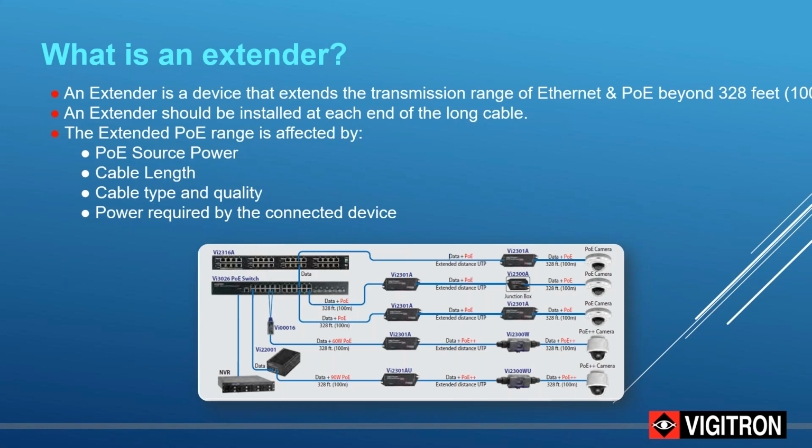When we talk about coax, or single pair for that matter, the extender has a dual function. And the dual function is not only to extend the cable, but to convert the signal to travel over those two types of cabling. So regardless of the length involved, when we deal with those types of cables, we're going to need an extender, even if the distance that we want to extend is under 328 feet.